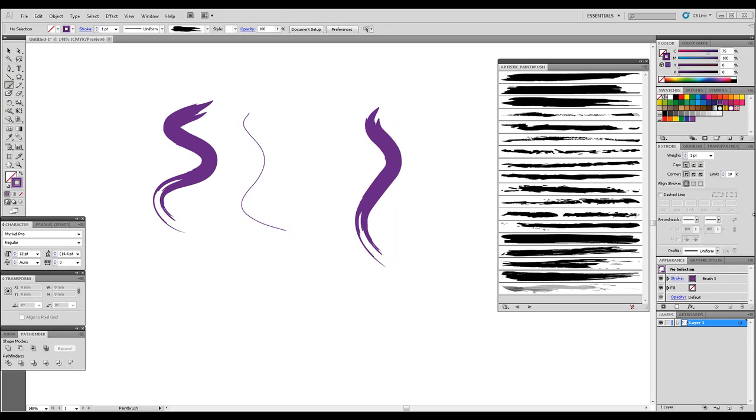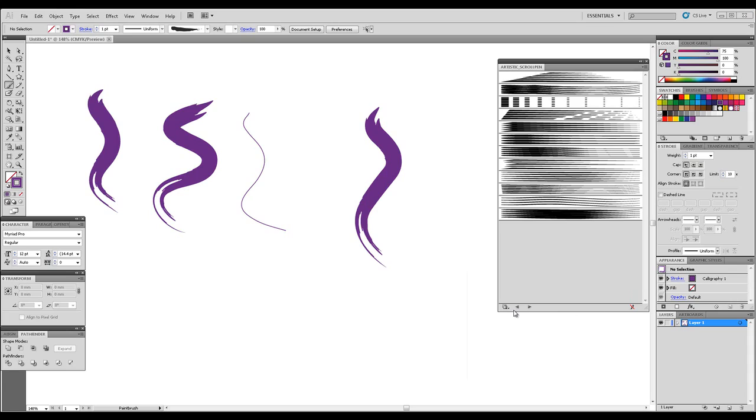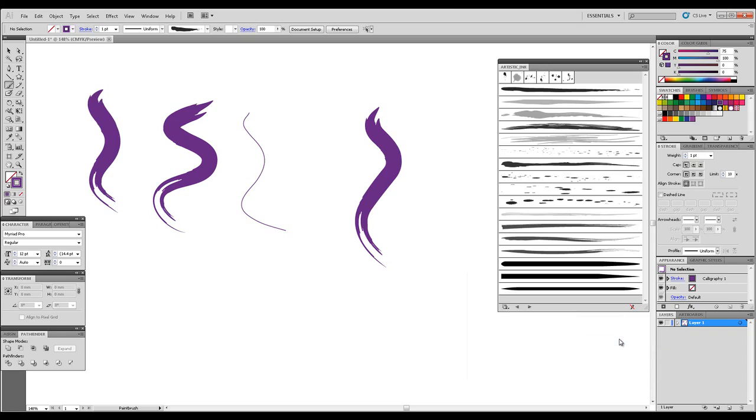It's important to note here that when we do select these artistic paintbrush effects, the stroke we have drawn with the pencil automatically converts to a paint stroke. Likewise, when we draw on the fly, or paint on the fly rather, it's the paintbrush that we use to do so. We might also select artistic and ink in the options. This gives us an inky pen kind of effect.